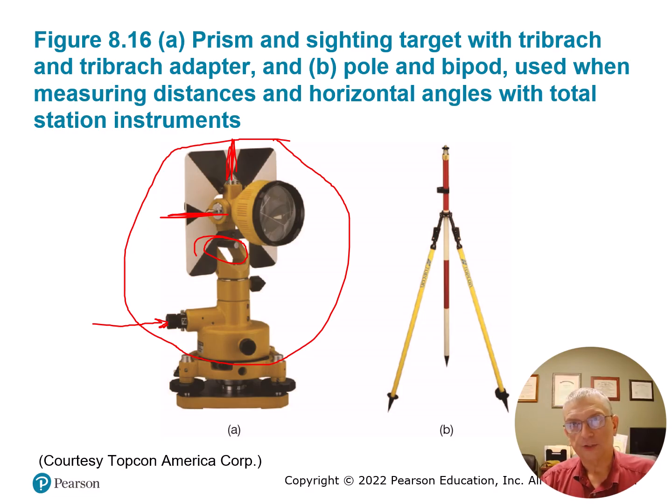However, we're just talking about this because it's simple and it's a good place to start. In modern practice, most instruments have laser plummets, and the laser plummet, in my opinion, is far superior to the optical plummet in daily operation. Now, it might not be if you're doing really high level geodetic work at night, but for boundary and topographic surveying in the southeast, including high dollar ALTA surveys, the laser plummet is superior to the optical plummet.